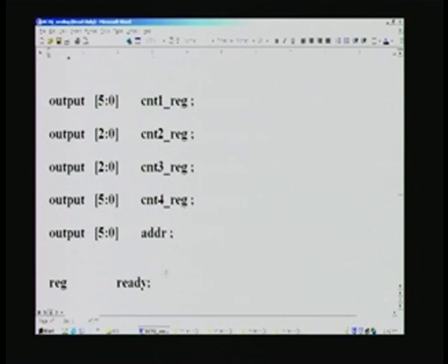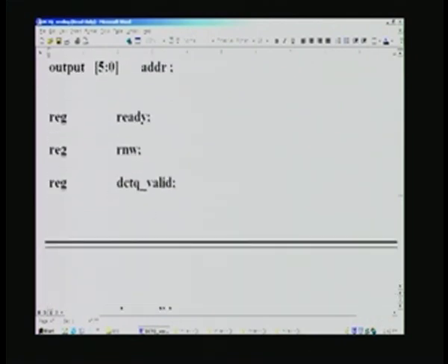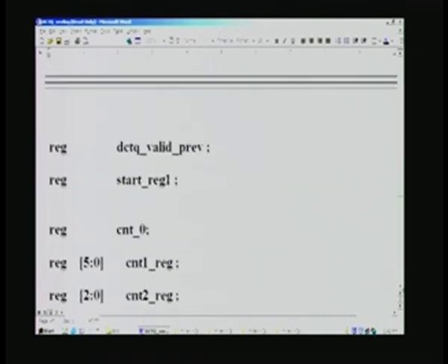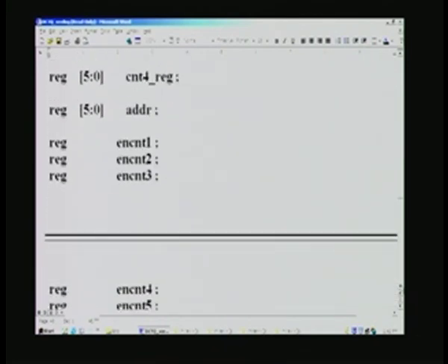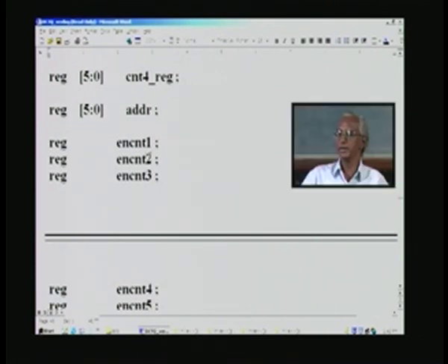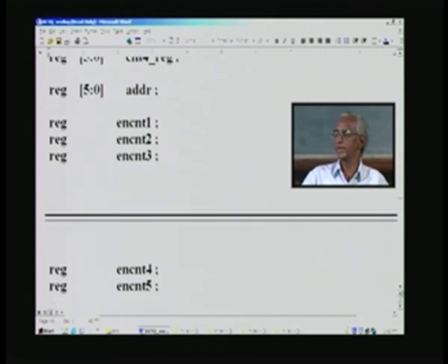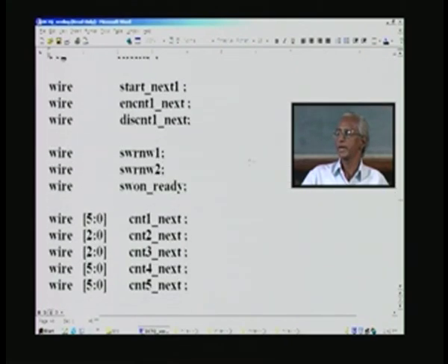and so also the counters and their bits here, and declare reg once again, and likewise the outputs here. As I mentioned before, we have 5 counters basically, and they also need enabling of those counters. So, we declare them as reg here, and we also need intermediate results, which we will cover later on, and for that these are all the signals that we use.